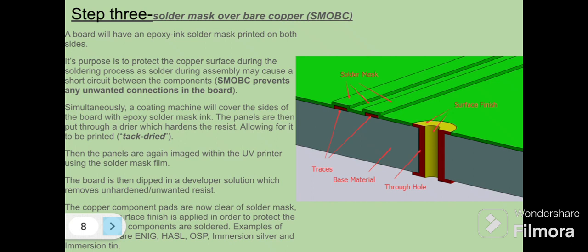We'll have sodium hydroxide developing on the PCB, which just gets rid of any impurities. Electroplating, which is interesting because it coats the PCB in metal, which can provide through-hole connections, but it can also increase conductivity, which is really helpful. And finally, etching, removing unwanted copper to make your rails, basically. And of course, after this chemical processing is done, the board will need to be cleaned because you can't just have chemicals all over your board.